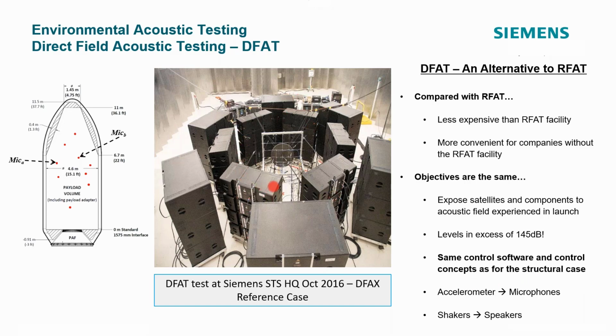Now the units and the success criteria are different because you're dealing with acoustics instead of structural vibrations. So instead of accelerometers, we use microphones, and instead of shakers, we use speakers. And this was done at our engineering services facility, in an acoustic chamber, a hemianechoic chamber where we did this testing.